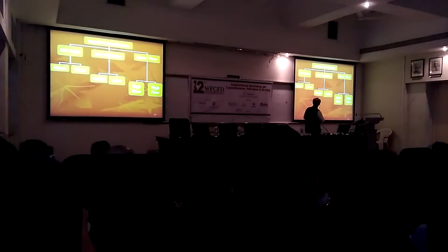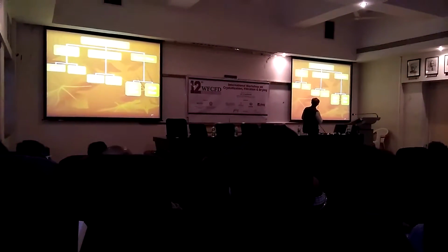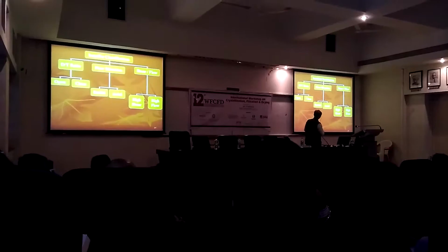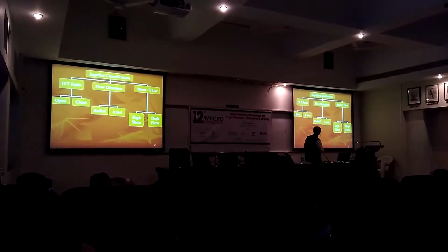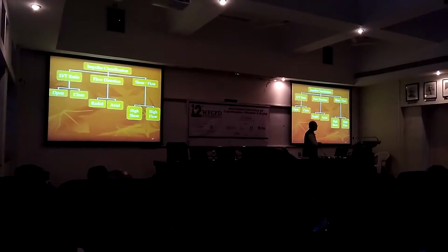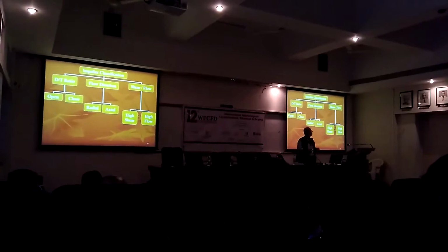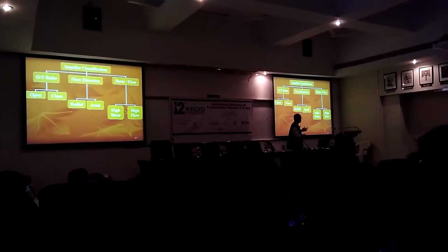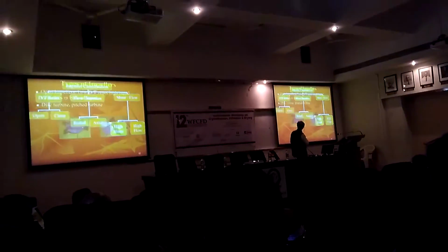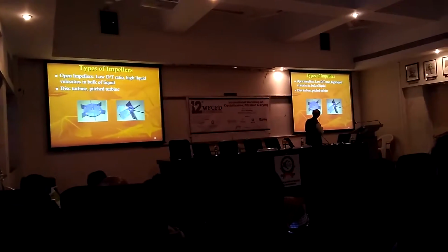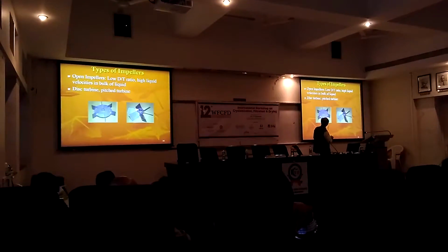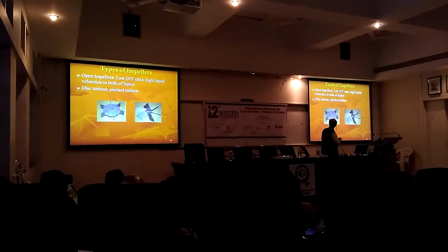size distribution. So you have open impellers, you have closed impellers, you have radial impellers, axial impellers, high shear impellers, high flow impellers or low shear impellers, which are typically different types of designs. I'll show you some designs which are currently used. These are radial flow impellers, open impellers, effectively operate with lower D by T ratio.